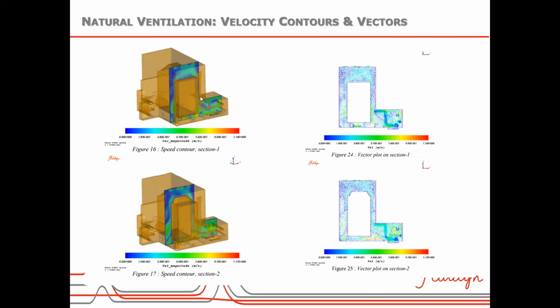Another important thing while doing natural ventilation is that the boundary conditions are very important, as I was telling even in the morning. To get good convergence in a natural ventilation case, the proper conditions are very important. For outflow, we specify a particular static pressure, but for inflow we will have a different boundary condition, which calculates the static pressure and forces it at the inlets.